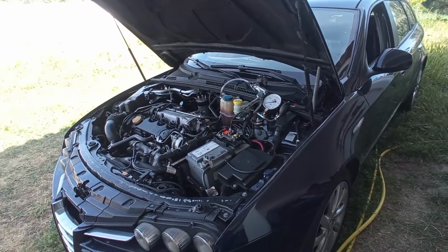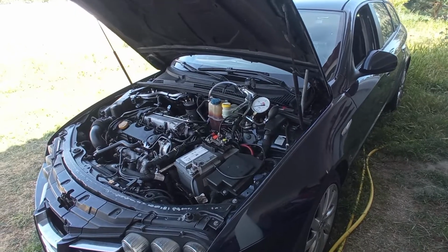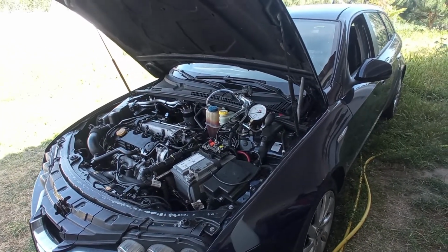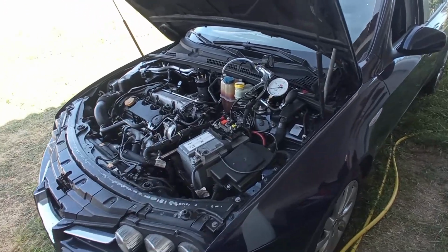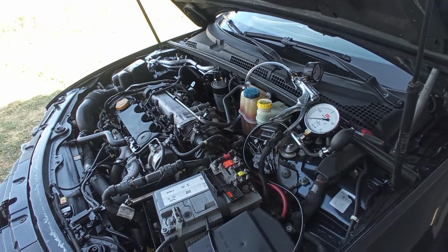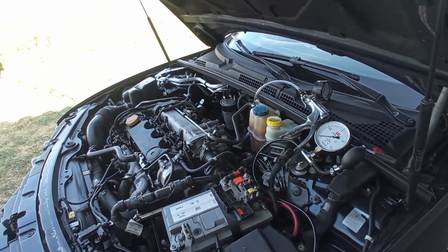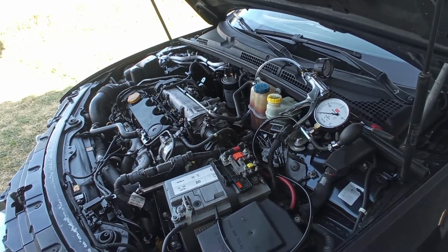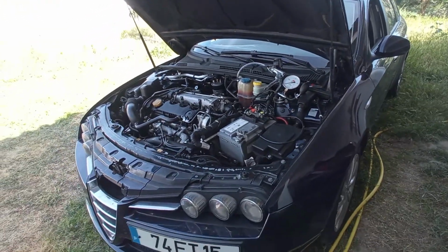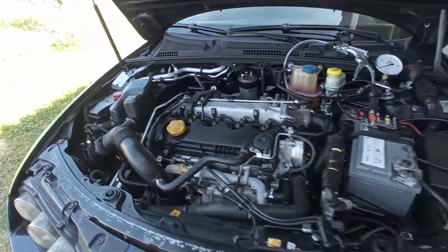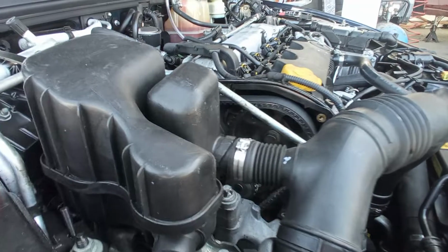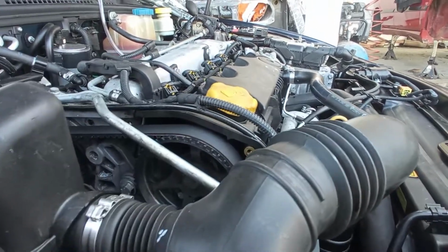Being this way, I have to talk to the customer, see what's what. I have to do now a full modification of the DPF system, put the blank on the EGR back in, but this time also using the correct gasket, the metallic one, on top of the blank, and try to see if I can save this. This is getting horrible, guys. So much work on this car, so much dedication, and it is not getting better, not at all.